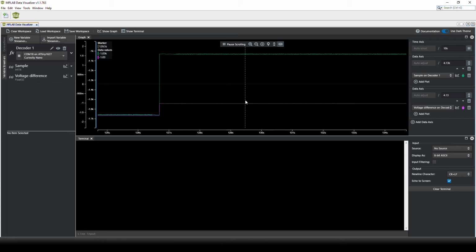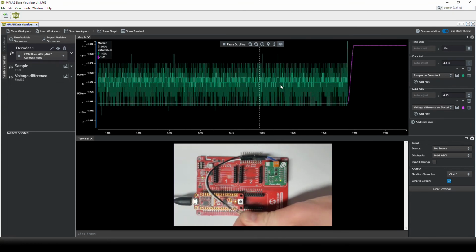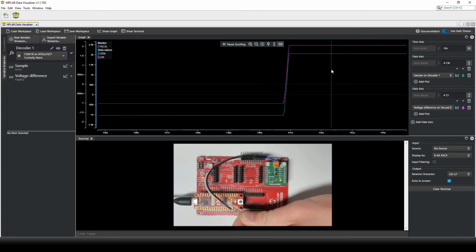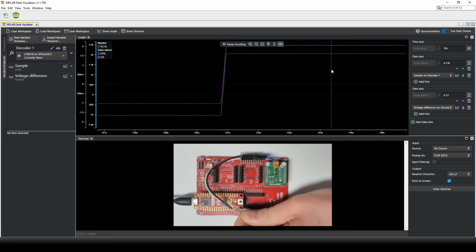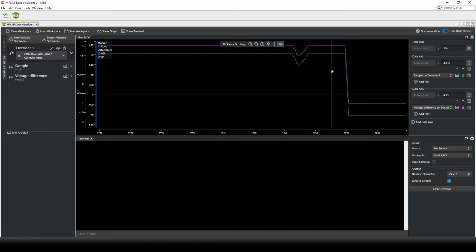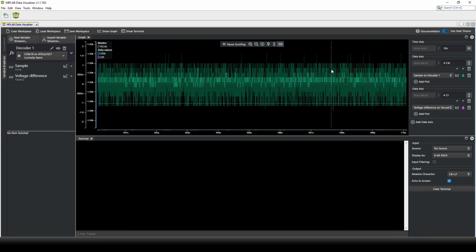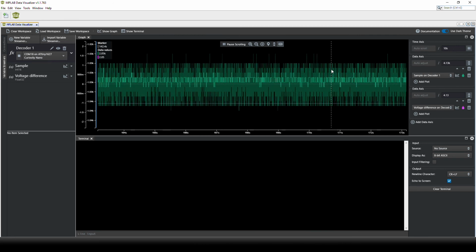So the low limit is now about 1.3 volts. And if we press the button, we can see that we are capped at 2.5 volts, which is a bit strange considering 3.3 minus 1.024 is 2.276. But this is because this value is greater than our reference value set at 2.048 volts. And this is why we are experiencing this clipping.